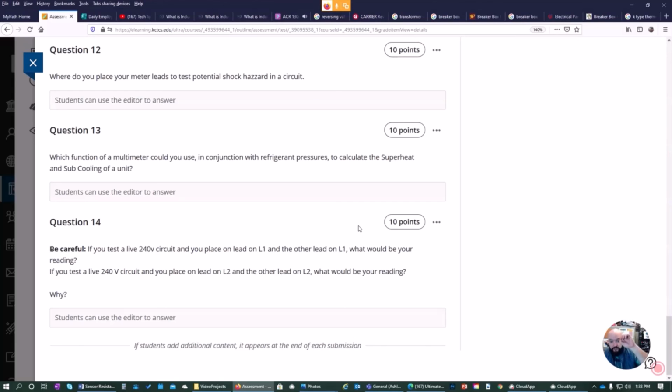So you can check the low voltage going just to the compressor, or low voltage going just to the condenser motor. Same thing. You can check the amperage going just to the inducer motor, or the amperage just going to the blower motor. The supply voltage is the supply to both components. The load is the voltage going to each individual component. Make sure you understand the difference. Any questions?